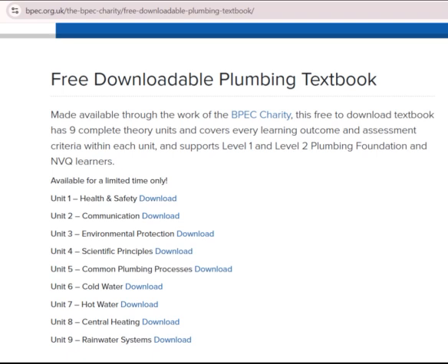Open vented systems. Feed and expansion system position. The feed and expansion system, F&E system, has three roles to play. A. It feeds the heating system with water during filling. B. It allows water to expand into it when the water is heated. Some expansion also takes place up the open vent pipe. Water, when heated, expands by 4%.